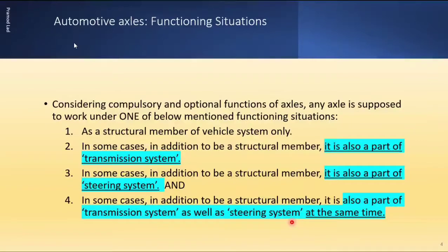Third situation is that in some cases, in addition to being a structural member, it is also a part of the steering system. So when the axle is located at the front, it carries the load, and in addition to that, it helps the vehicle for steering. Its wheels will turn as per the steering system design and they will perform the vehicle turning function.